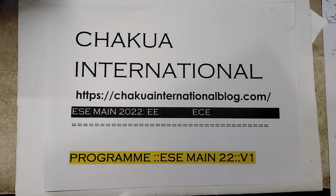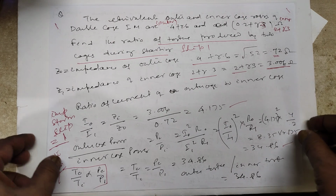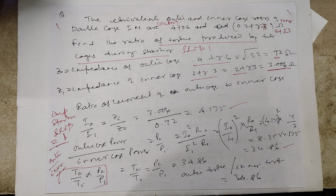Here the one problem is coming from double cage induction motor. What is the purpose of double cage induction motor? The outer cage has more resistance as compared to the inner cage, causes more impedance, as a result less current, less torque at the starting. In starting, the motor is started mainly because the outer cage having more resistance. Running constant torque is produced by the inner cage. That is the main purpose, the advantage of the double cage induction motor.